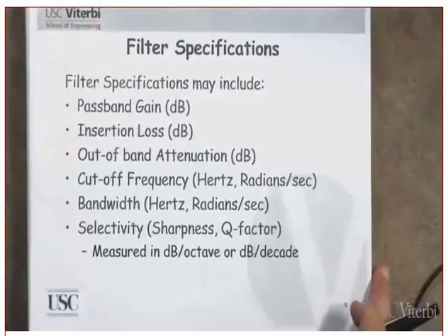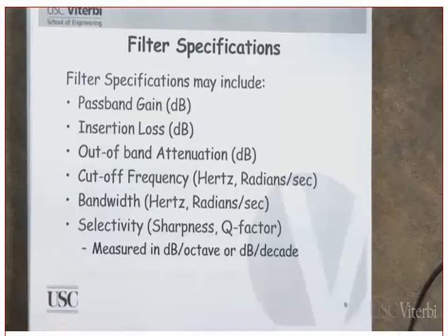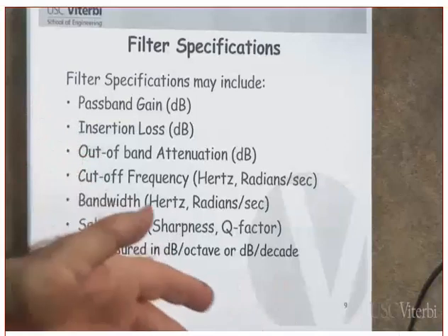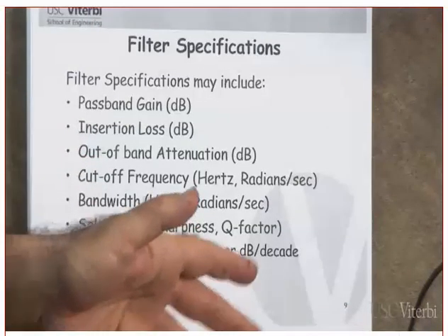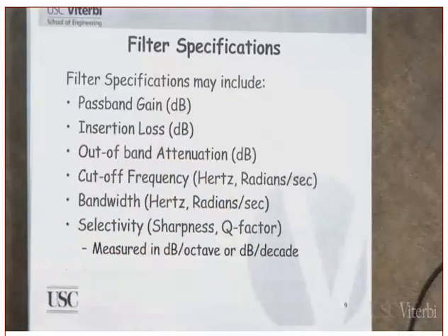Why do we want to change the phase? For example, when you want to generate what is known as SSB, I will show you that shortly. SSB stands for single sideband, as opposed to double sideband. We will see when we get there that those two bands, the upper sideband and the lower sideband, have the same information. So why are we sending them? We need only to send one of them. You follow me on that? When we want to send one of them, we need to do phase inversion of the entire spectrum, so that when we add them together, they will cancel with each other. You follow me on that?